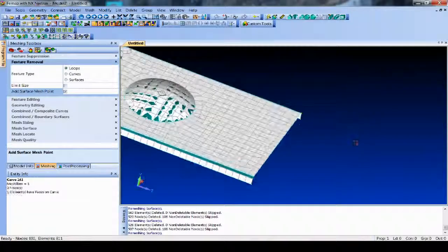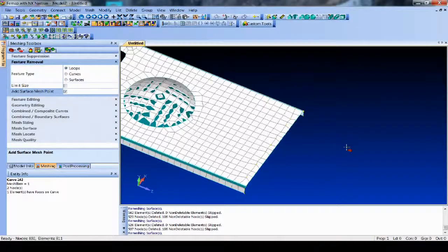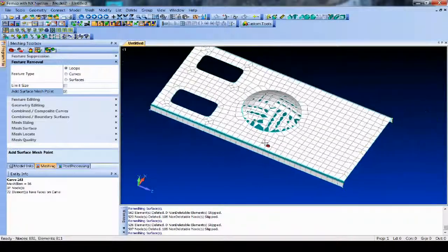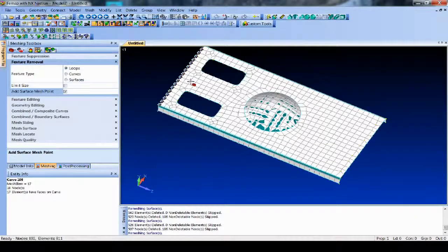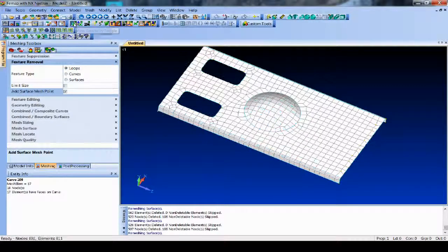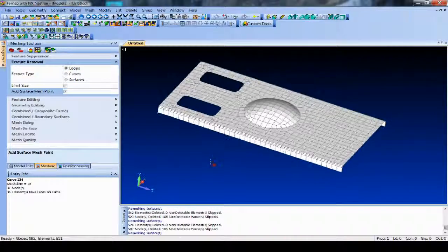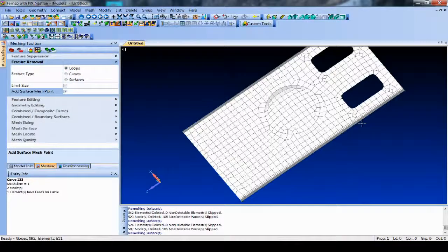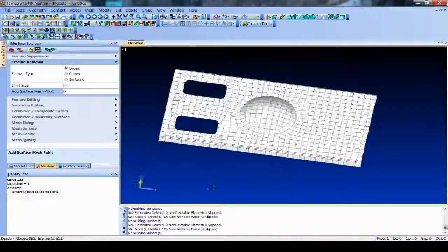So at this point we've now taken the existing mesh, created geometry, cleaned it up real nice, and have a decent mesh for dynamic type analysis. Just turn off the underlying surfaces, and I think you'll see we got a really nice mesh at a much coarser resolution.